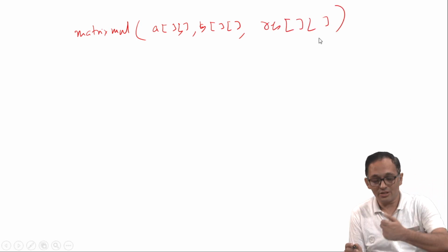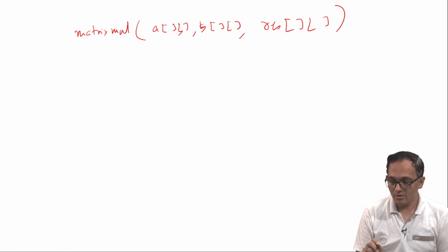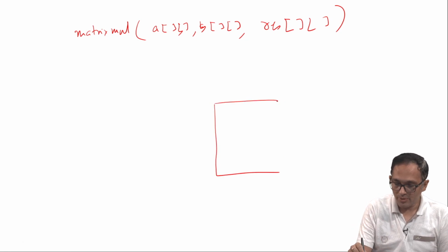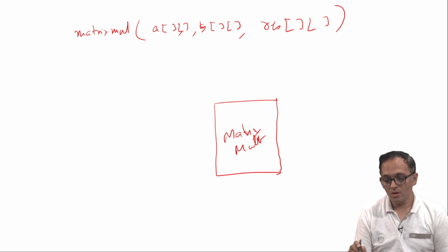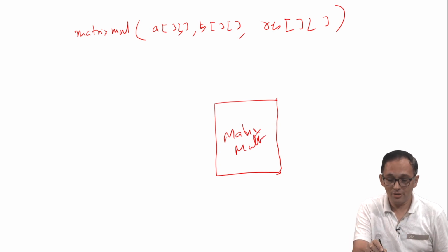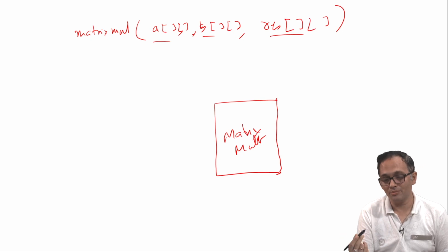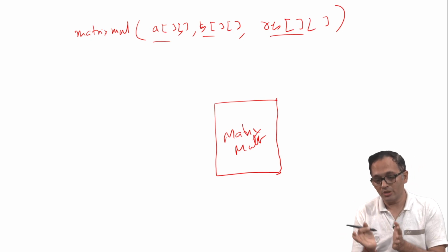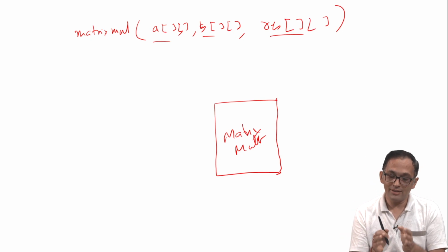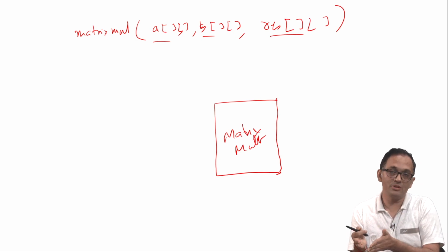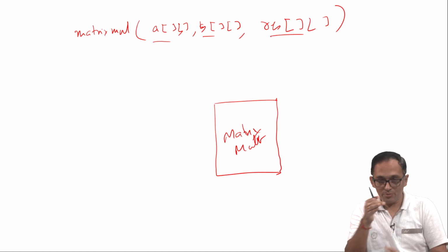So, this was your C interface, but in hardware when you generate this, this is the module corresponding to matrix mult. But where are your arrays A, B and C? The high level synthesis tool assumes that since this is a 2-dimensional matrix, it is kind of a memory, it will be mapped to some memory, and the memory is outside because this is the interface, because they are not inside this matrix multiplication hardware, since you are passing them, right.